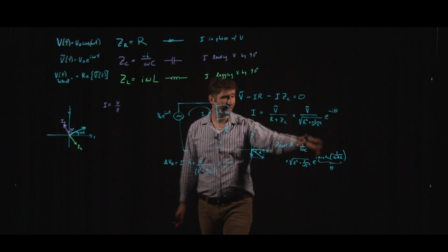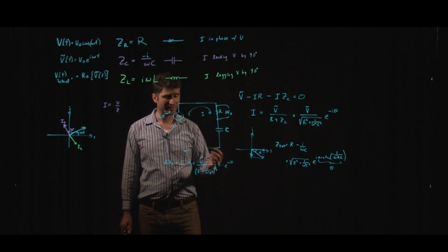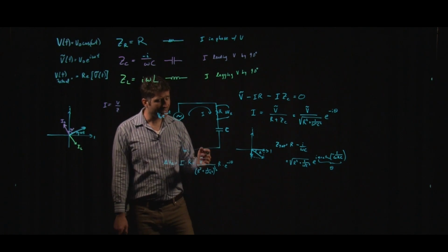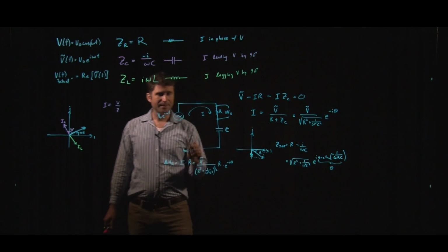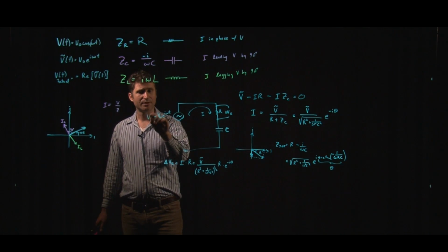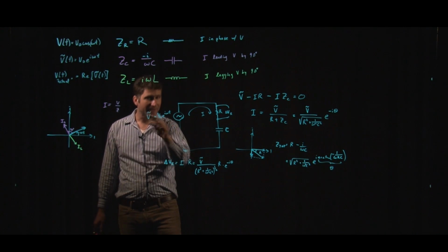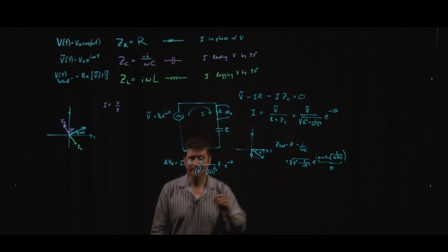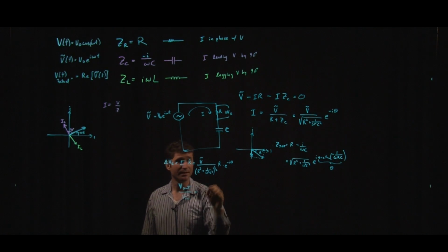And I'm leaving the theta as defined like this just for the sake of not having to write too much right now. One thing that's really cool here is that I said we could define a transfer function, which is basically the voltage drop across the resistor divided by the driving voltage. So I could see that my V out, measured across the resistor, divided by V in, which is my driving voltage, is just going to be equal to all this stuff divided by V tilde.